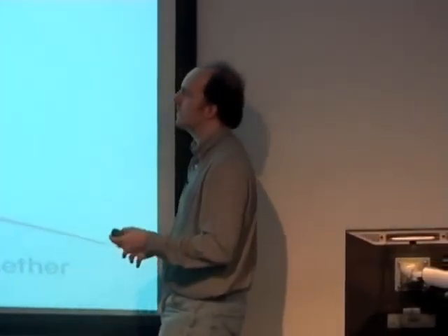And to determine the time response, you get the transfer function in the s domain, you apply your input, you then go back to the time domain using inverse Laplace transforms, which are on the tables which you will be provided with. You're not expected to remember them. Like I said, if you're having trouble wondering what Laplace transforms are all about, and you want to read more, go to your maths notes. I think you're doing them at the moment, for some of you at least. Some of you perhaps did it last year, but it's all standard maths.